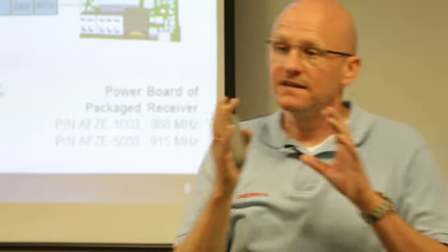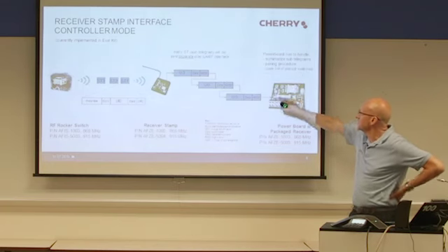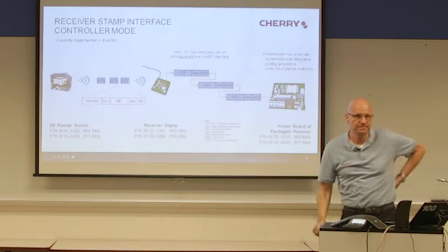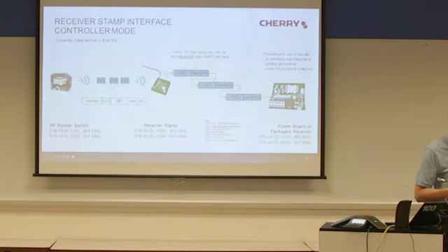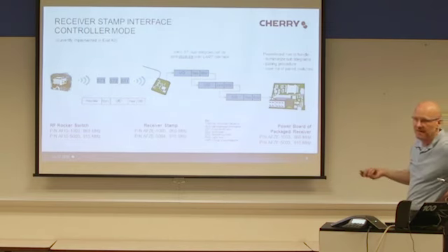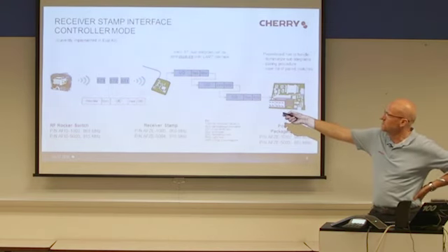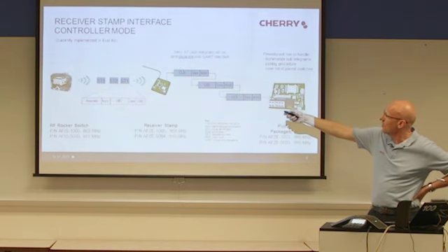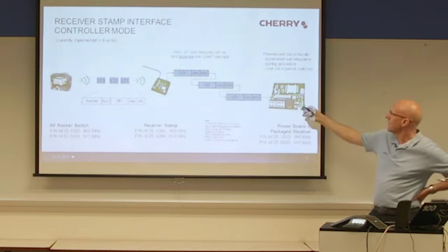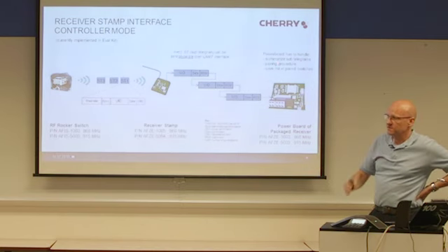So now when the customer wants to use the RF stamp standalone, he has to implement all this intelligence on his own electronics. And this is a high effort for him. Because we can give him an interface specification where all this data is described, but he has to handle all these points: summarizing the subtelegrams, the pairing procedure, and saving the list of paired switches. Not impossible. He can do it. But it's a high effort for him.